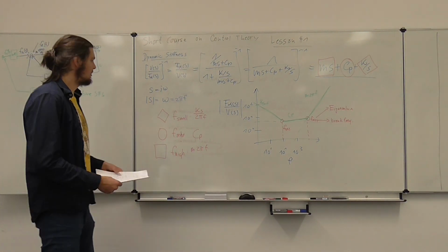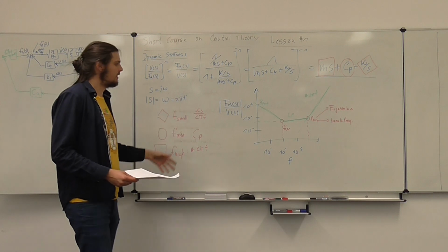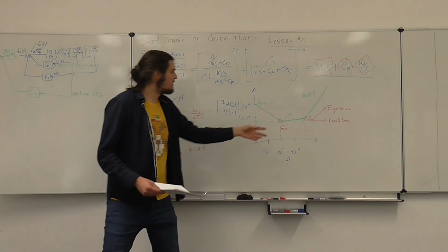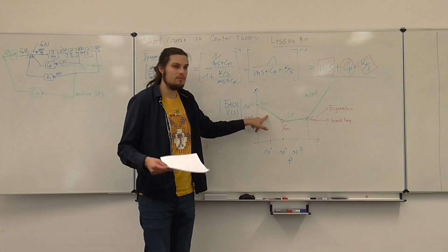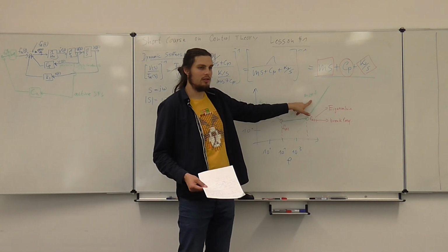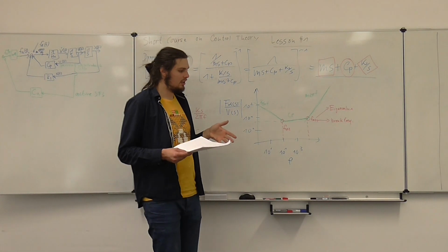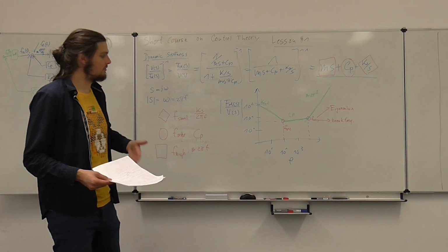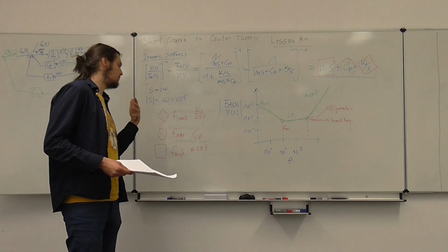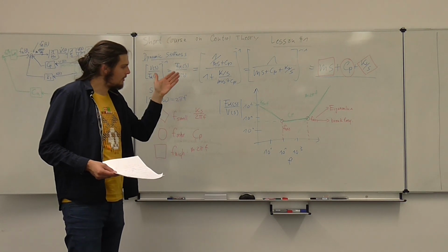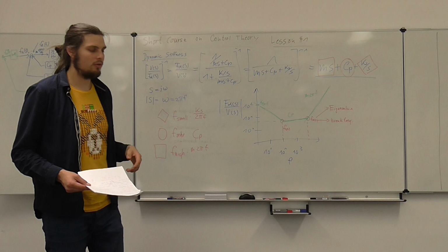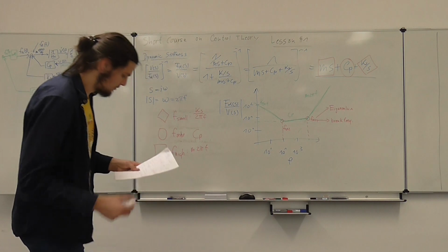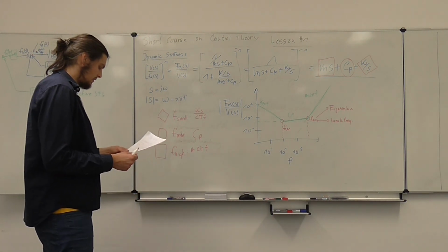Okay? So I hope this makes a little bit of physical sense, like how these interact and how they look from a disturbance. The same is for your current control. This basically looks like your resistance, this looks like an integration, for instance the I of your control, and this is your L. So you shape basically the impedance that your grid sees. And you should shape it wisely, because if you don't, it might do something weird, or it might be oscillating, or something like this. So always rather think about this when you create your state feedback controller, than thinking about the command tracking. Because we will see, command tracking usually is not that big of an issue. You usually use feedforward to do this.